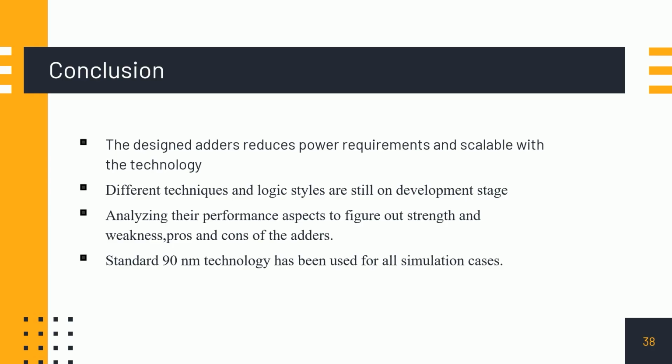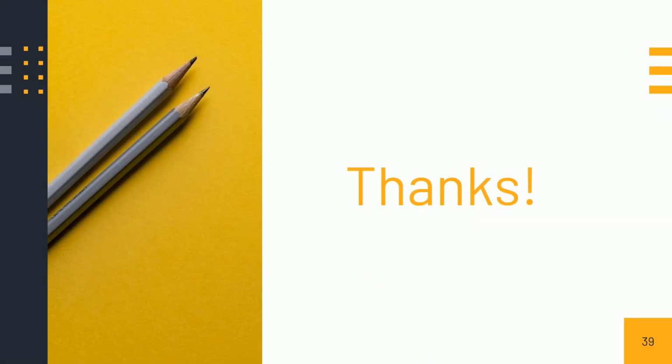For analyzing performance parameters, the adder cells have been implemented and simulated using Cadence Virtuoso tools. Standard 90 nanometer technology has been used for all simulation cases. We believe that the comparative analysis among full adder cells in this paper will enable VLSI designers to find out the best suited full adder cells depending on system requirements.